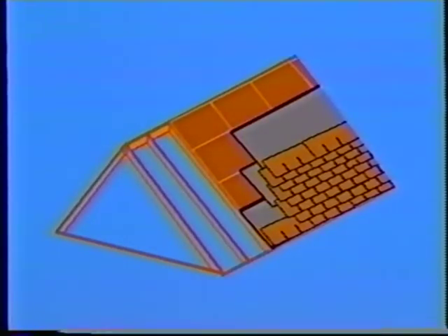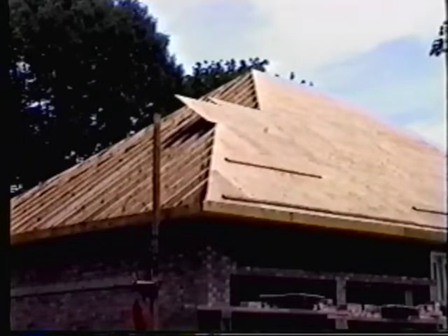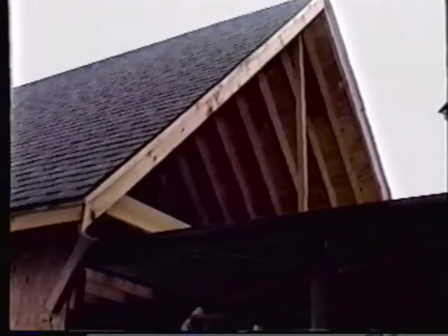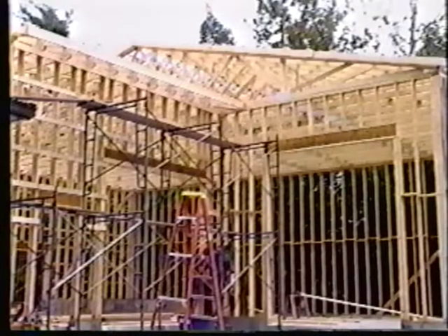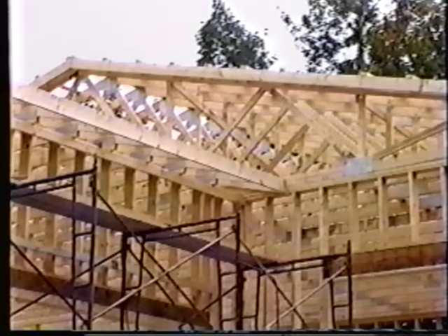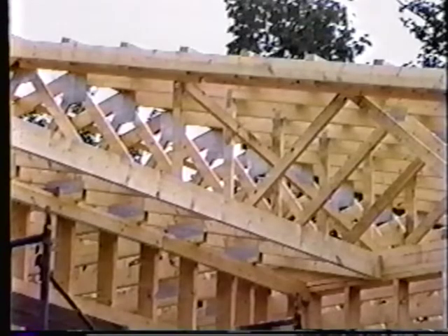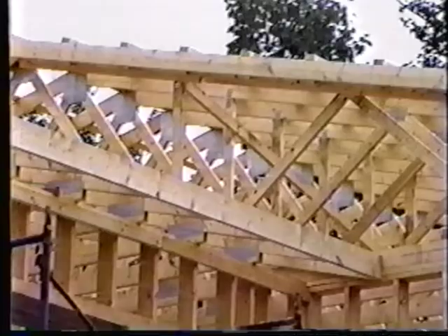Roof assemblies are comprised of three basic parts: rafters, decking, and deck covering. Rafters are usually of dimensional lumber and are used to span the distance from outer wall to ridge pole or another wall. Common dimensions of rafters run from 2x4s to 2x10s. They usually are found 16 inches on center. Newer homes may use lightweight truss assemblies, in which the largest piece of wood used is only a 2x4. Common spacing for these trusses is 24 inches on center, but some may be spaced even wider.